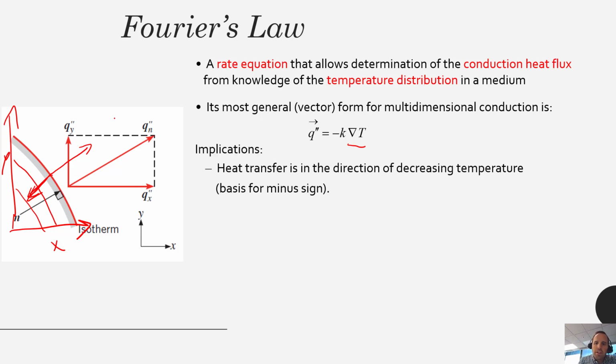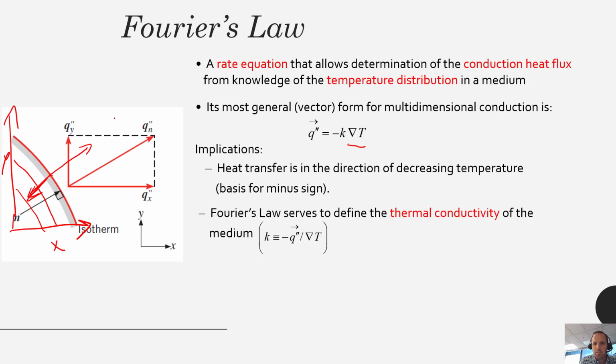So the negative sign is really important there, and it has a really important mathematical meaning. It says that heat flows in the direction of decreasing temperature. So heat is going to flow downhill. If we have this topographical map and we're able to plot things out with increasing temperature represented by these lines, then our heat is going to flow downhill, against the temperature gradient.